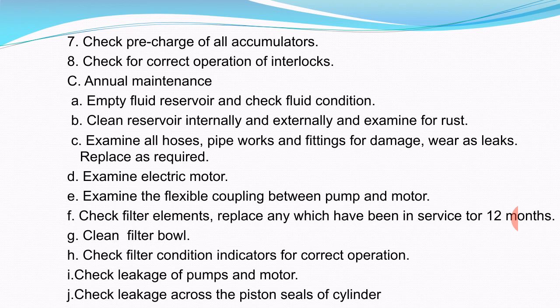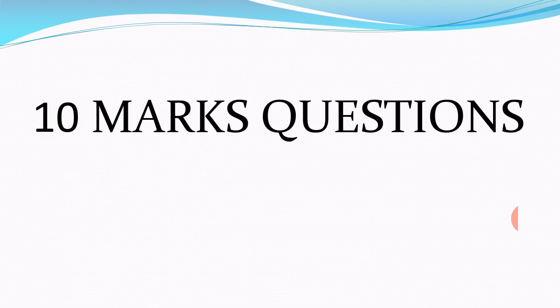Check filter elements. Replace any which have been in service for 12 months. Clean the filter bowl. Check the filter condition indicator for correct operation. Check leakage of pump and motor. Check leakage across the piston, seals, etc.